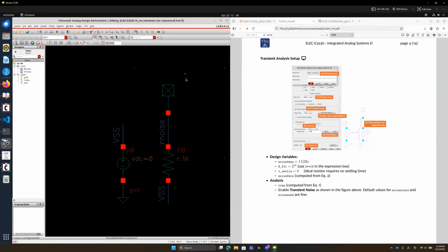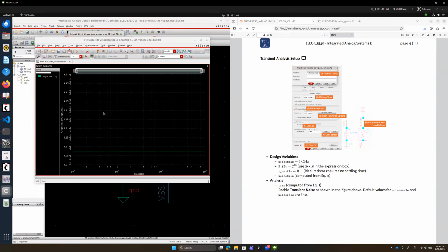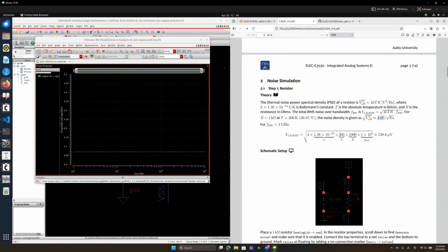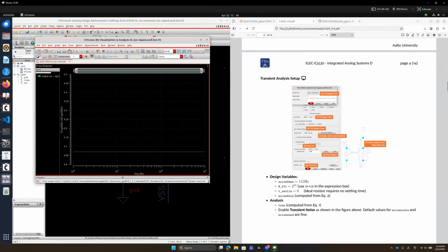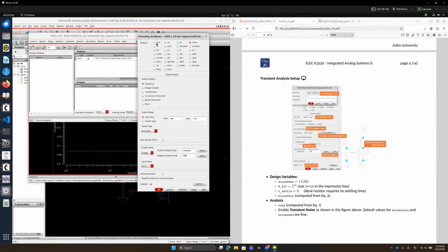Okay, so you can go to output noise, volt per square root hertz, magnitude, and click the plot. You can find that it is approximated. Of course, there is some deviation, like 4.07. It's not exactly the same as 4 nanovolt, but it is approximated to 4 nanovolt per square root hertz here. Okay, at this condition, let me set up the transient noise simulation.